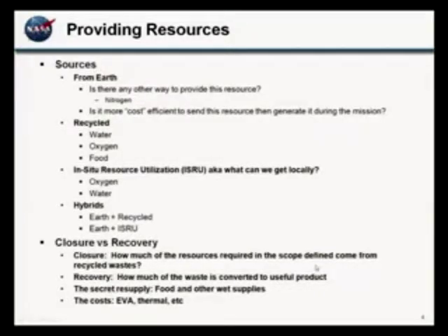We've moved away from pure oxygen systems because of the fire and flammability risk. It's just too extreme. And especially for a long mission where you need more habitation accommodations, you're going to have a hard time finding non-flammable options for all of them. So we have looked at argon as something that could be considered. It is another gas that is not going to interact much with the human body, but would keep your flammability risk down.